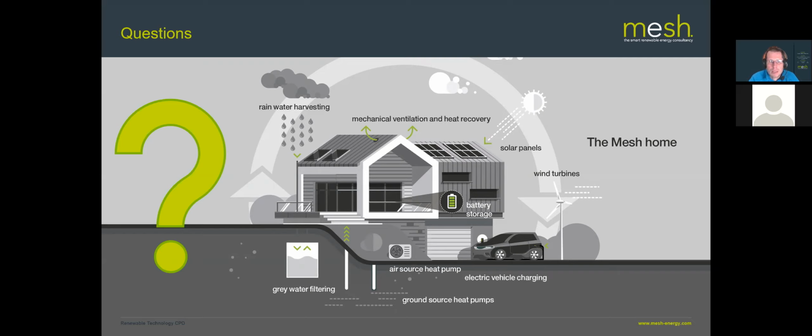The crossover point, generally speaking, is on houses that are around about that 15-16 kilowatt thermal mark. At that point, that's where ground source starts overtaking. Now, there's obviously lots of other moving parts that go into those equations. So things like land availability, how easy it will be to do the collector installation for ground source, electricity costs, solar PV inputs, all kinds of other things that can change that equation. But that's a good starting point. Anything over about 15 kilowatts plus, ground source is likely to be pretty competitive. Anything below that, it's more likely that air source will be competitive.